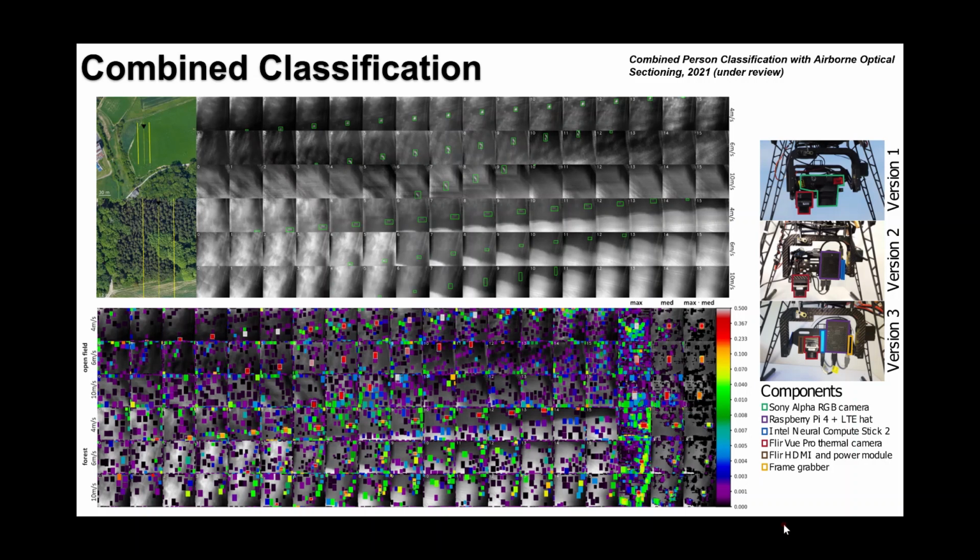So in terms of classification, we have achieved a couple of improvements. So far, we could only fly with our drone with a speed of 1 meter per second. That was limited to the imaging speed of the camera that we used, which could only record 1 frame per second. We changed the imaging system to achieve a recording speed of 30 frames per second, and with that we can allow the drone to fly with a maximum speed of 10 meters per second.